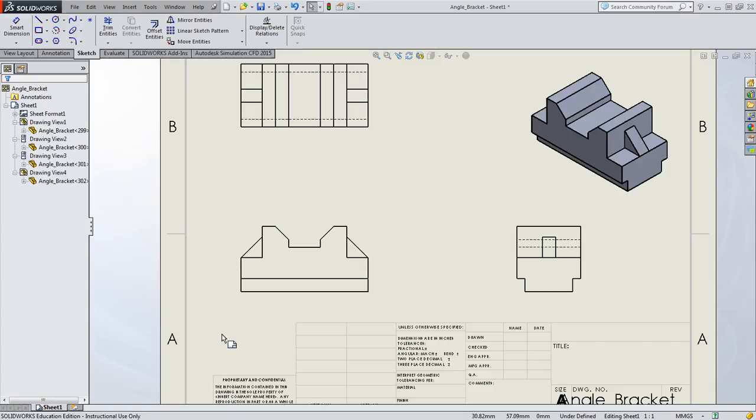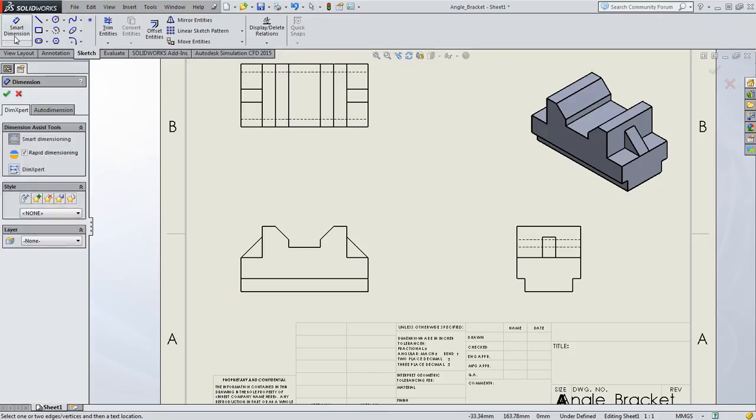I know that there was plenty of room over here to specify angles. So the baseline worked. And if you notice, I only did half because this part is symmetrical. If you only show half the dimensions in a baseline dimension, you imply that this is a symmetrical part. Whoever reads this is going to assume that a professional did this correctly, and the reason they left off the dimensions is because it is symmetrical. They're not going to assume that a student did it and decided to just stop working. Okay, so we haven't really gotten anywhere, I know that, and I apologize, this is long-winded.